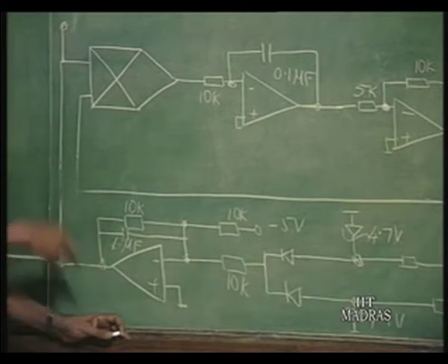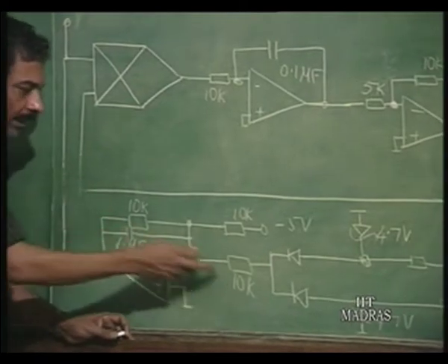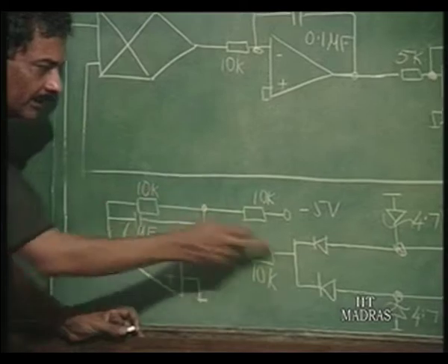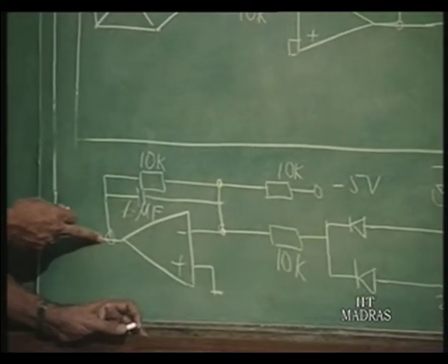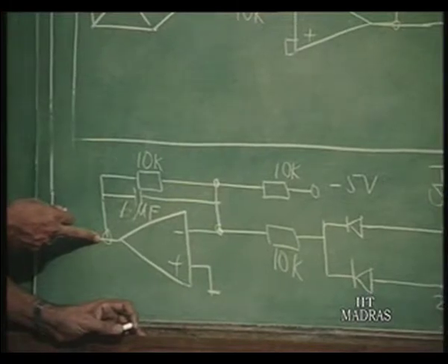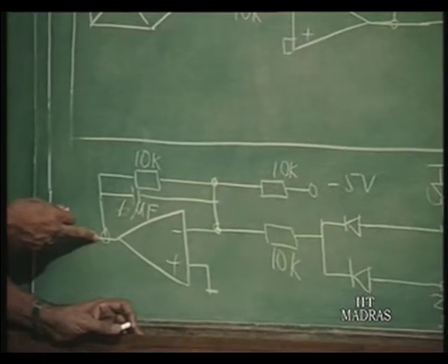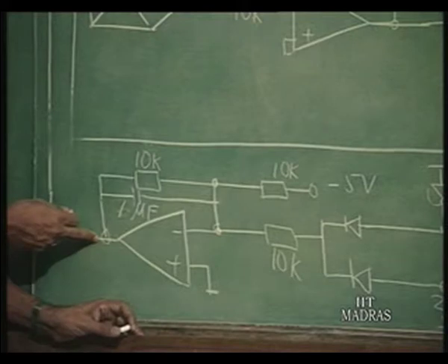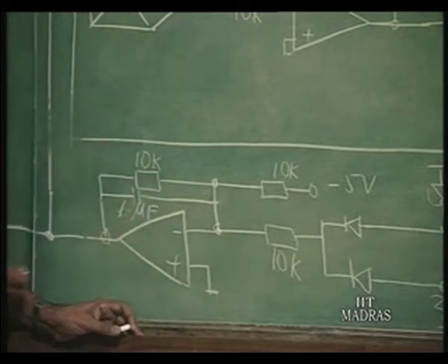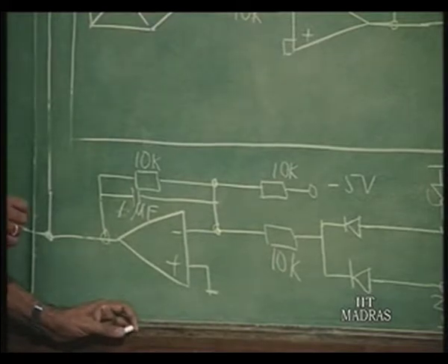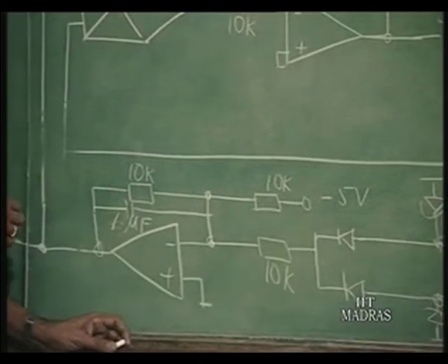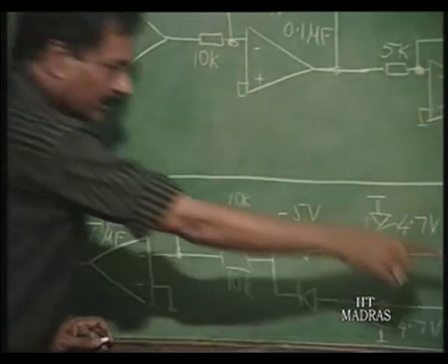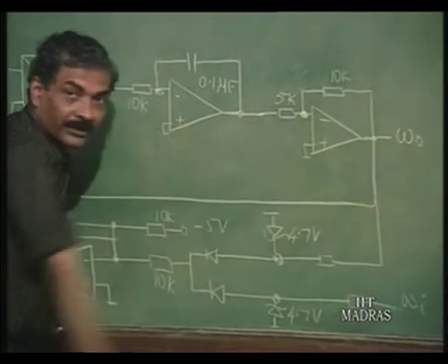slightly reduced for this. Earlier the gain was pretty high, and actually when the gain was high, this DC voltage was also high, the op amp was going to saturation, and we could not very clearly see the actual theoretical limitation of the lock range, etc. earlier. Here now you can clearly see the lock range and how this phase lock loop will get locked to the incoming frequency, which is here, and this is the output frequency.